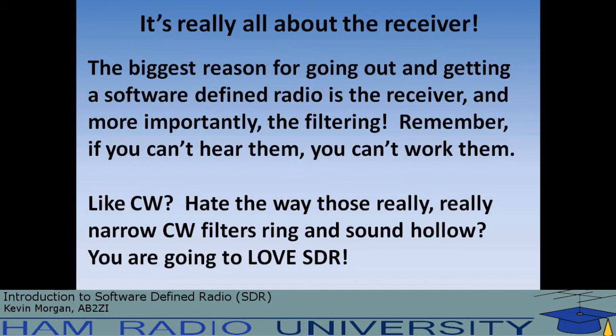I usually record it as an audio file while I'm doing the nets, because it's nice to be able to, if someone's got an audio problem on their radio, or if they got feedback, or if they got a hum, it's one thing to be able to tell somebody, hey, you've got a hum in your audio. It's even better if you take that audio file, cut a little clip out of it with Audacity, and email it to them. Say, here's what you sound like.